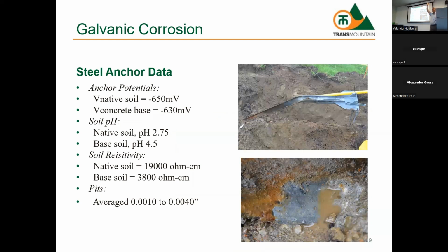It's all radio communications towers, power lines. Large structures have antennas on top of their building. Why? Because they're going to get struck by lightning. They're metallic, they're going to get struck by lightning. So all structures like this have to be grounded so that when it does get struck with electricity, it goes to ground. And the best metal to use for grounding is copper. You use like a 2-aught, very thick copper cable to ground most things, right?